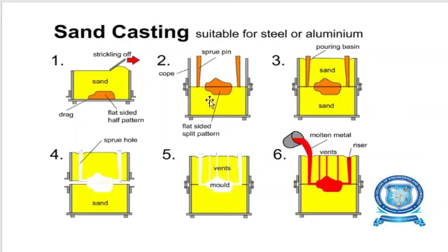After ramming, the cope and drag molding boxes are split, and the split patterns, sprue pin and riser pin are removed. Again, the molding boxes will be assembled and locked with the help of dowel pins. After that, vent holes are prepared for escaping gases during the molding time.